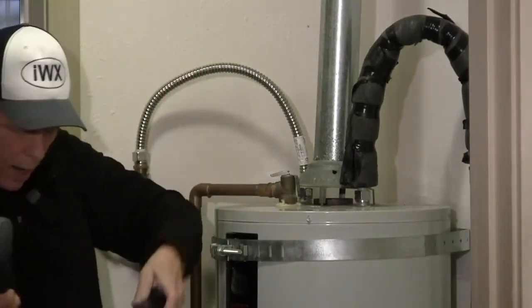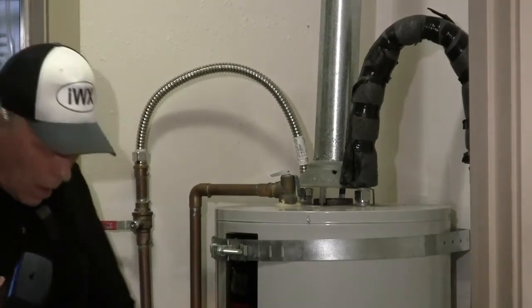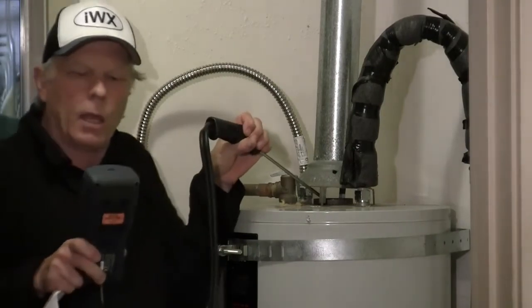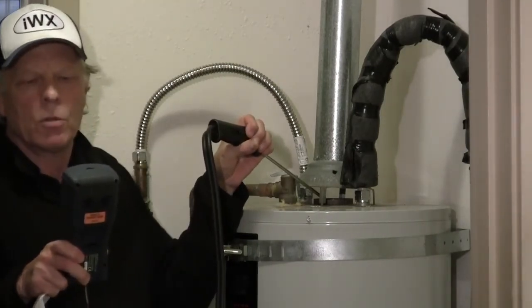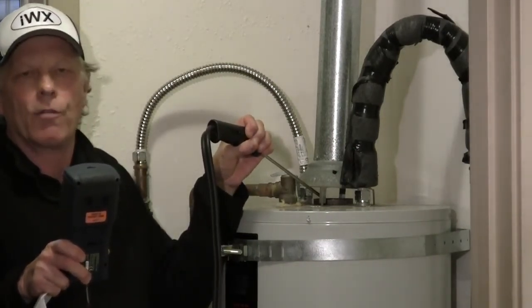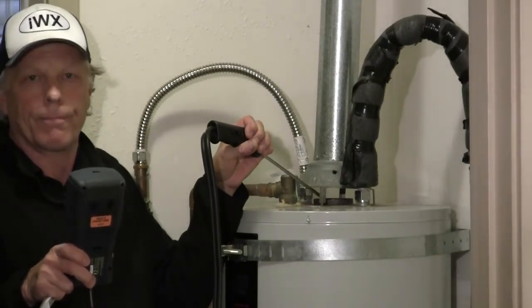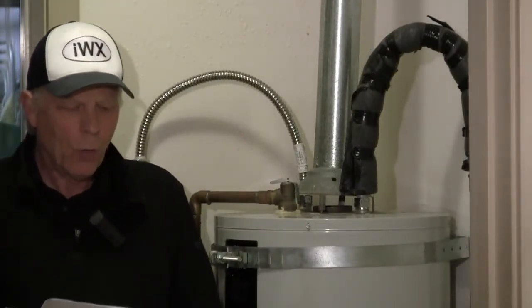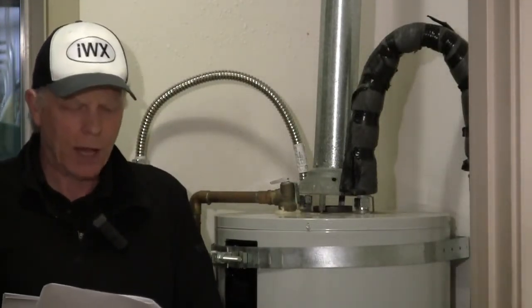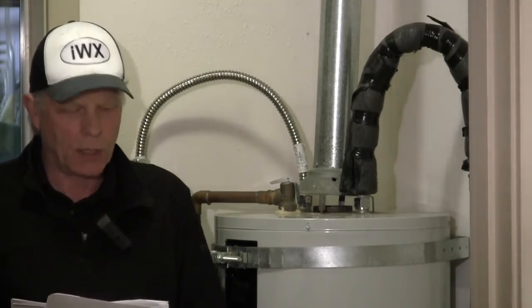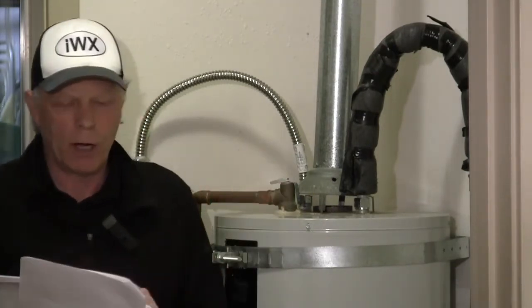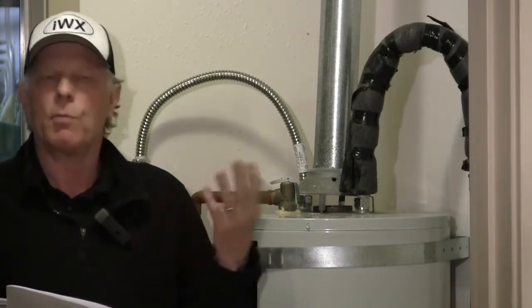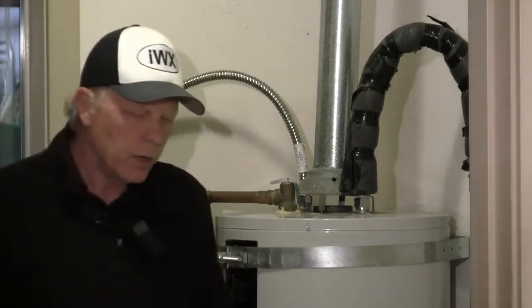So we're going to take our test below the draft hood, and I'm getting approximately 27 parts per million air free of CO. Okay, we're on line 2, where the candidate has to apply the correct action level based on the test results for the CO in the flue of the water heater, and they need to reference the current ANSI BPI 1200 standard.